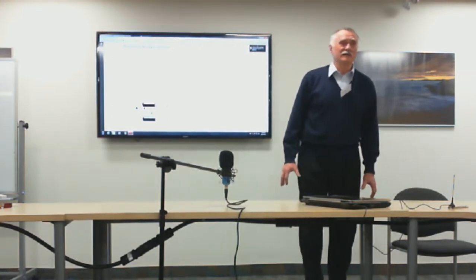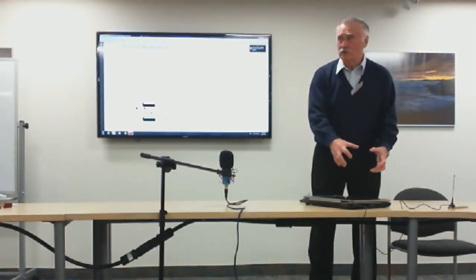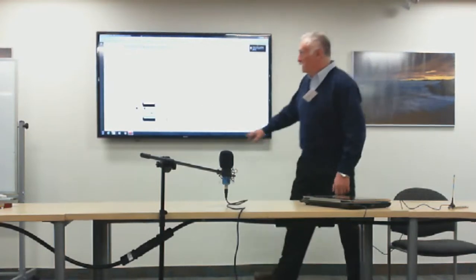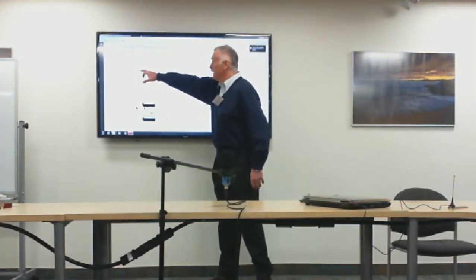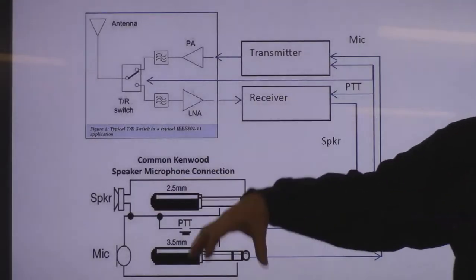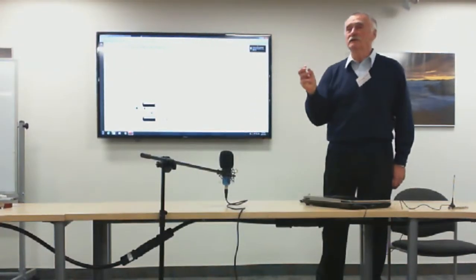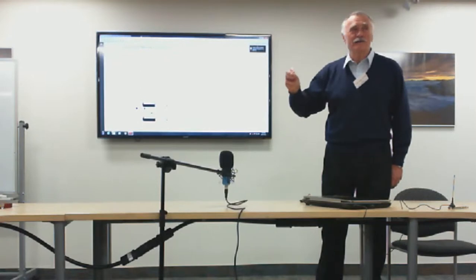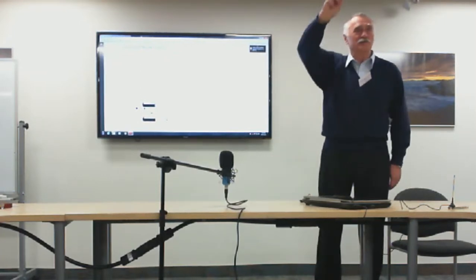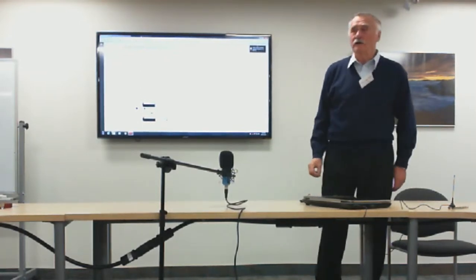However, when you have a transceiver, a transmitter and a receiver both in the same enclosure locally, then this switch is eventually inside your transmitter, and there is only one single coaxial socket, and one single coaxial cable is going up to the tower and connects to the antenna.